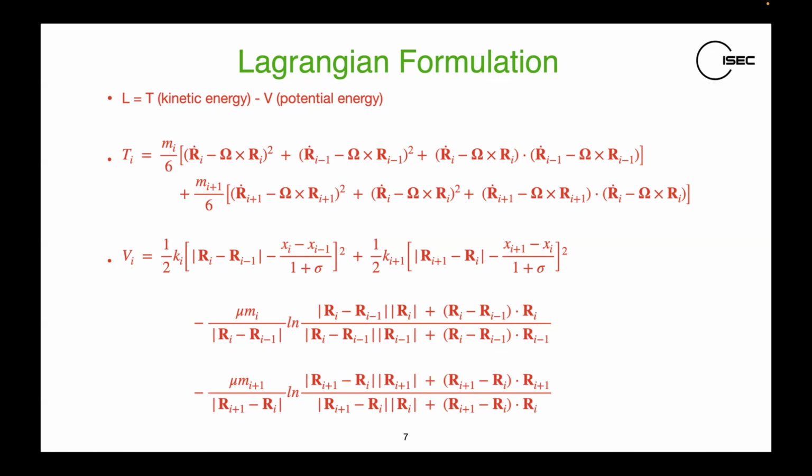And one more interesting thing is the kinetic energy. So if you write down the kinetic energy, you're expecting a term like 1/2 mv squared, and instead you see this factor of 6 coming in. And the reason for that is that you have an extended mass spring. And so not only do you have 1 second derivative that you have to put in your Runge-Kutta, you have 3 for each node that you're solving for. And these are coupled, so that adds complication to the solution of the problem.